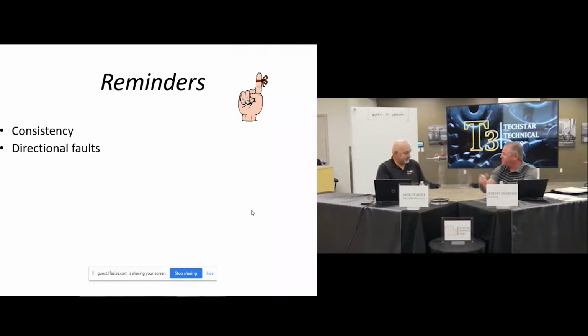That's a great example of a conversation you often have: if I put one sensor on this bearing, will it capture what I need? Well, it may or it may not. There are a lot of situations, just like you described, where the vibration is predominantly in one plane and it's hardly even detectable in the other plane. That's right. So that's something to consider when you're installing systems, if you're debating whether to add that second horizontal sensor or that second vertical sensor. There's definitely times for that, and that's where the triaxial might work well for you.